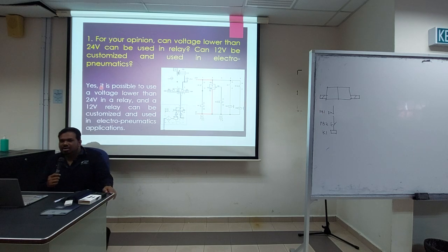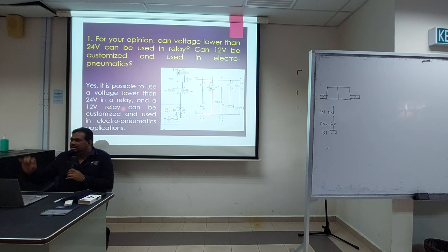Similar lah. So when you want to buy something, so go and check the data sheet ataupun the specification yang diberi oleh manufacturer. So dalam tu dia akan bagi tahu, so whether this particular relay boleh gunakan 12 volt ke tak. Kalau dia cakap relay ni only can be used for 24 volt, so maksudnya you kena gunakan 24 volt lah. You cannot use 12 volt.